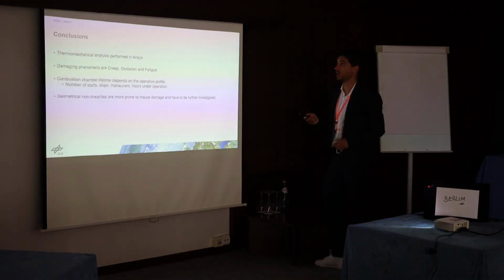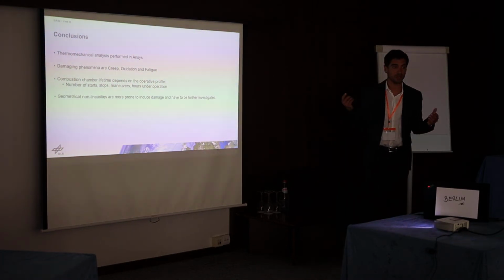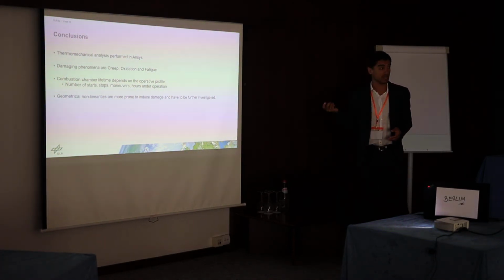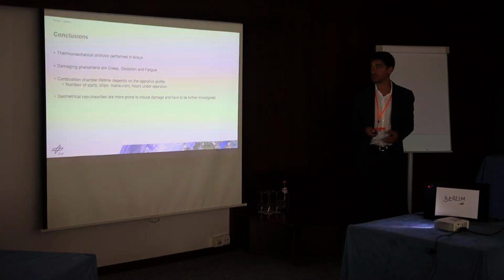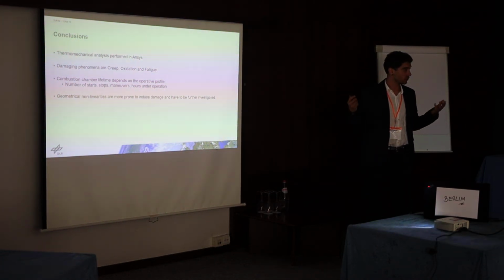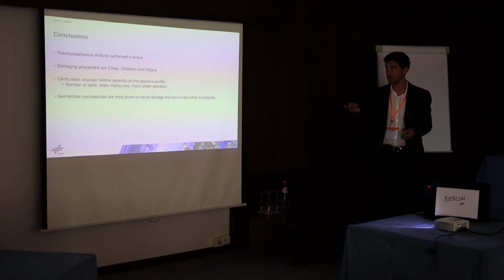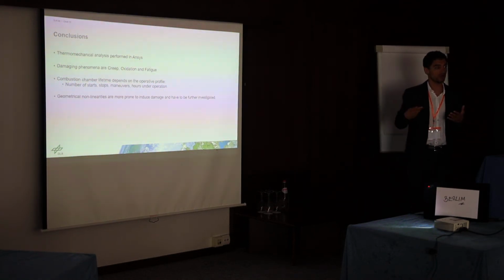So summing up my conclusions, we are still performing thermomechanical analysis in ANSYS with this user programmable feature in order to assess the lifetime of combustion chambers in micro gas turbines. The damaging phenomena involved are creep, oxidation, and fatigue. And the lifetime strictly depends on the boundary conditions of the system.